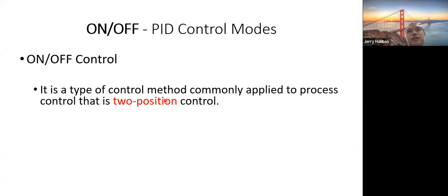Fiesta brands was once using an on-off control in their process control system, particularly for their sterilization, pasteurization and drying, particularly for their dried coconut or desiccated coconut. So they were using an open or fully closed pneumatic control valve. So there is no intermediate.